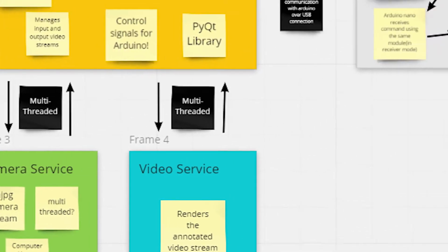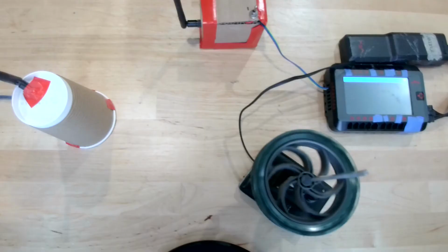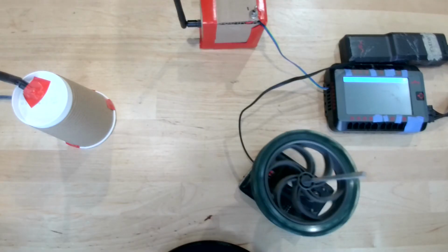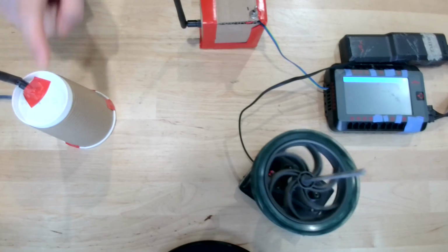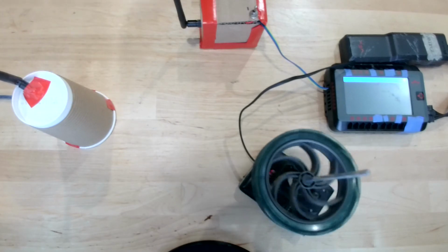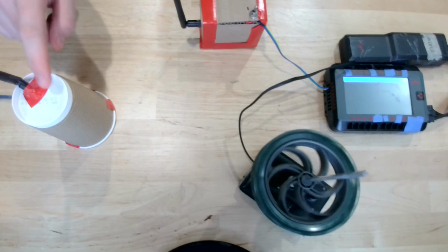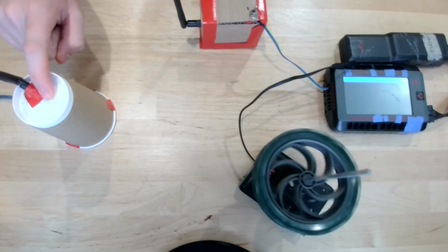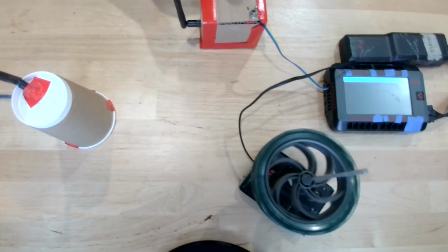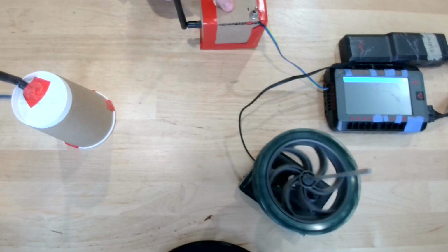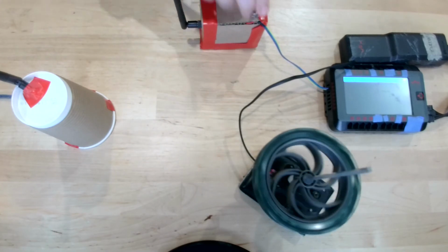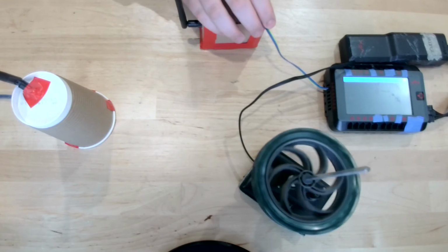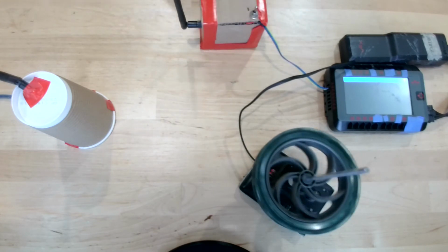Next, let's see how we made our Arduino control bridge. Here is a quick demonstration of the Arduino control bridge. In this container here, we have an Arduino Uno, which interacts with our GUI and receives an open or close door command. From there, it uses its NRF24L01 radio module to communicate with this Arduino and send it that open or close command. This Arduino then controls an NPN transistor switch, which regulates the current flow between the yellow and blue wires inside of this 3-pin wire.